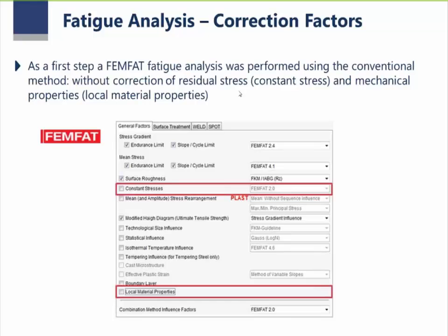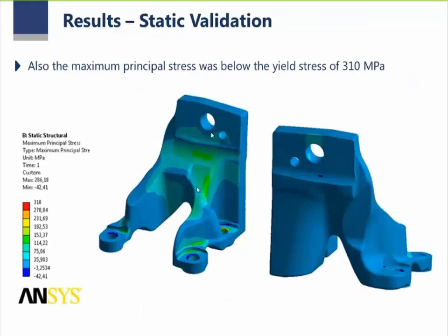For example, if MAGMA gives me traction forces for this region, perhaps it's a bad situation for fatigue. If it's a low value, no problem, but if it's a high value, perhaps it's a problem.